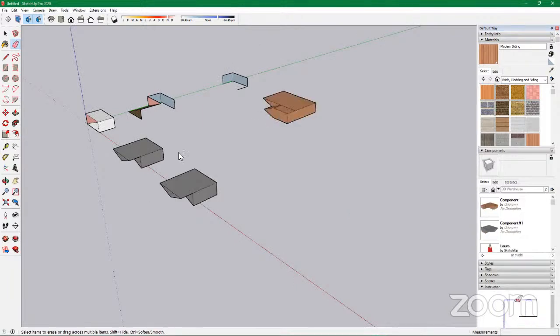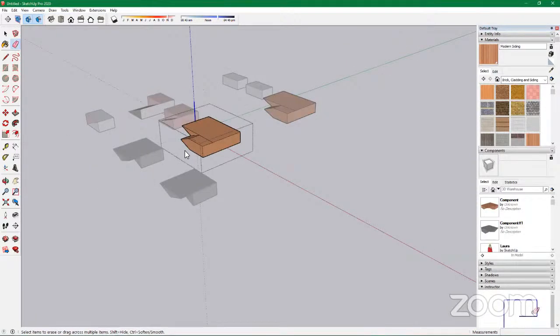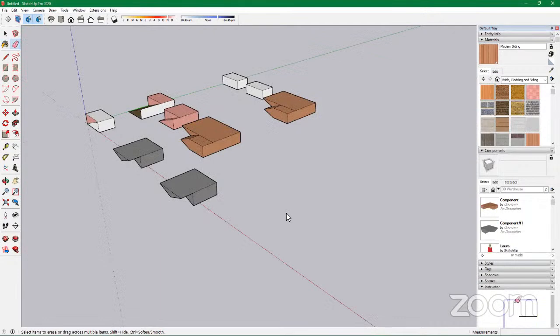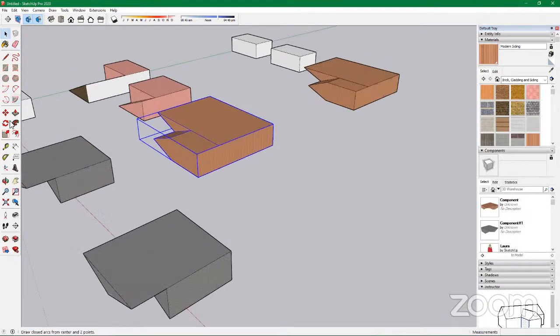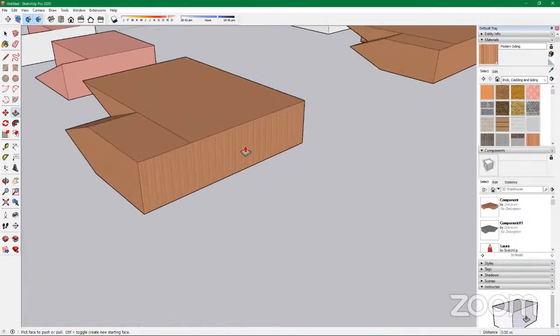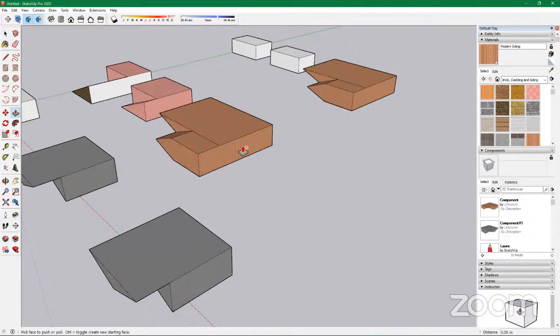Okay, with the eraser tool, once you select it, editing outside the component won't work. First of all, editing outside the component won't work. Let's say you want to edit this now. I pick my push-pull and decide to do this. You see that caution sign there? It means that it will not work. But you can draw on top of it using the component there as a place marker.